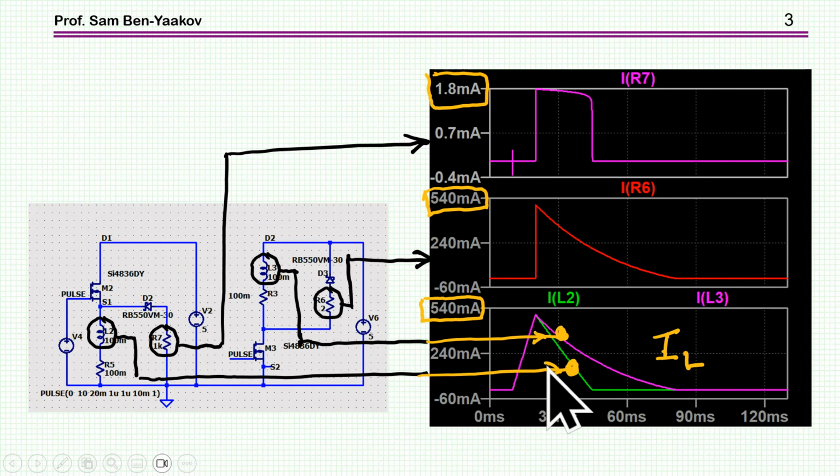Here I'm showing the current of the inductors. This is the conventional topology. This is the current of the inductor, and this one goes down, as would be expected, exponentially when the diode is capturing and there is some resistance, both the 2 ohm and the internal resistance, which is small. And then we have the current in this case.